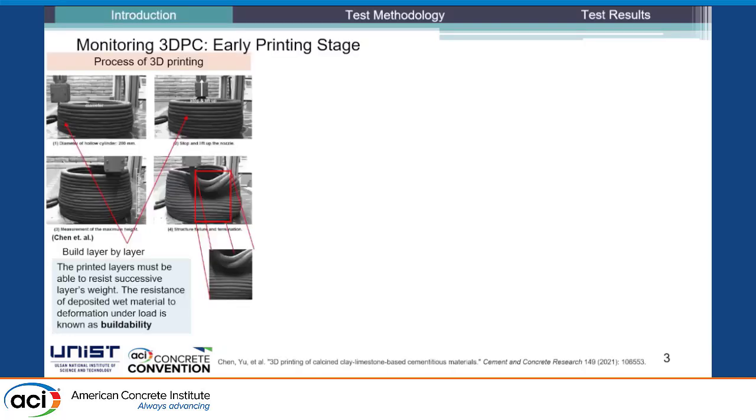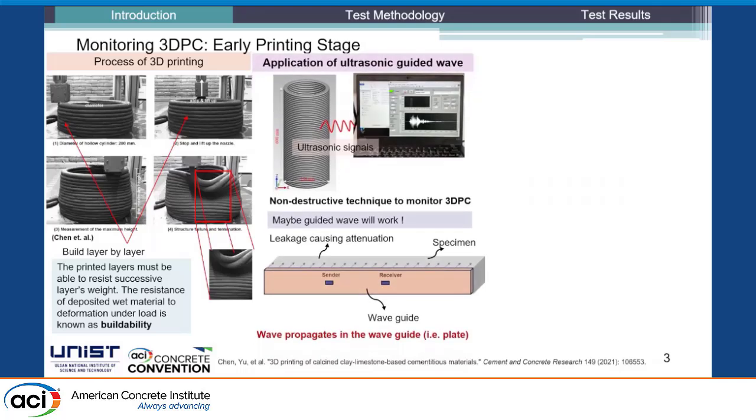So first, the main motive for our study, which is monitoring 3D PC in the early printing stage. When we print this kind of concrete layer by layer, there tends to be some kind of failure in between. So we would like to send signals through this fresh state so that we can monitor such failure. But it is quite difficult to send signals in concrete during its fresh state, so we thought that maybe a guided wave might work.